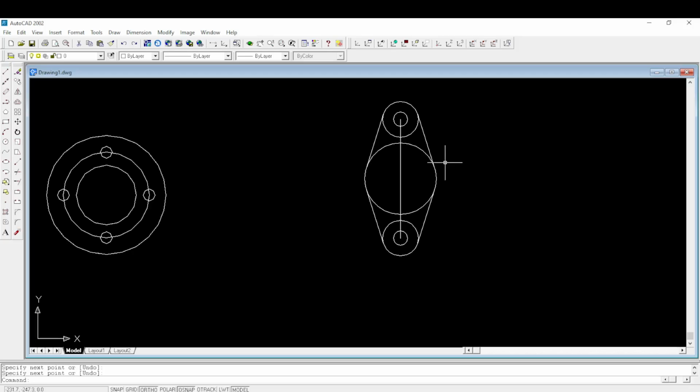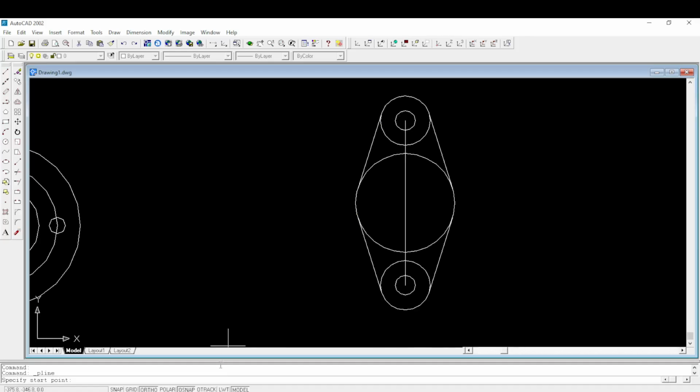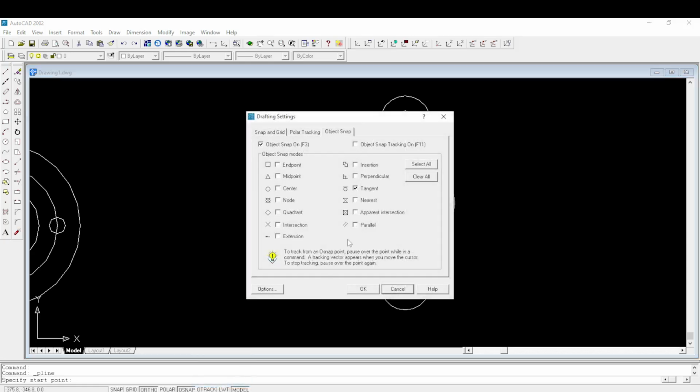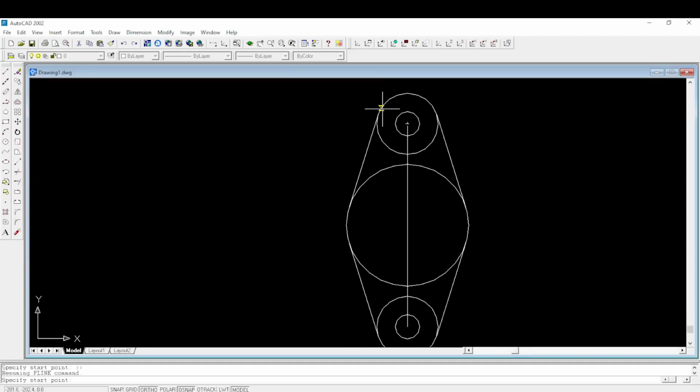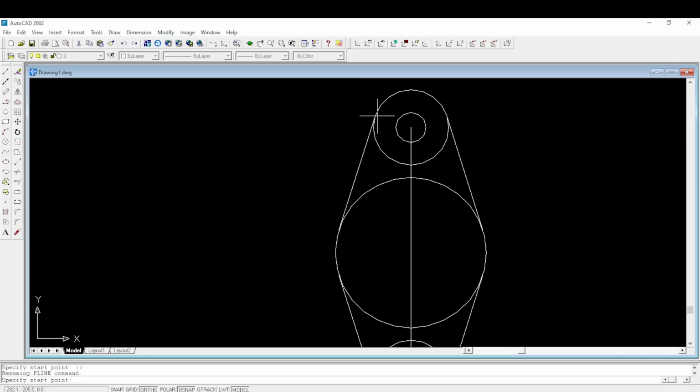Later on you can now use polyline on those lines. So polyline, you first put this all on again, so that you can select all, then okay. Our end point here, where our line was ending, click that point, then we join to that section.